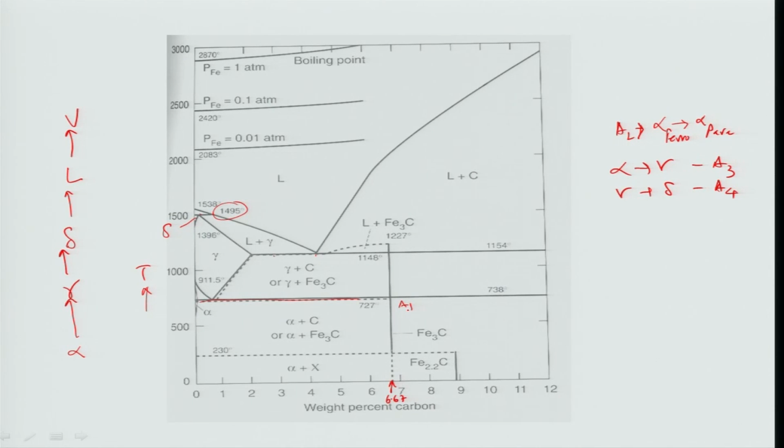And this is the reaction which is the eutectoid reaction I told you about in the last class, gamma going to alpha plus Fe3C. This is what happens if you cool gamma iron below 727 degrees Celsius. Remember, this temperature is also a function of composition. Therefore, we always use A1 as a symbol to denote this temperature. This can vary depending on the concentration of the alloying elements and many other factors. Okay, so this is the reaction we should concentrate on.